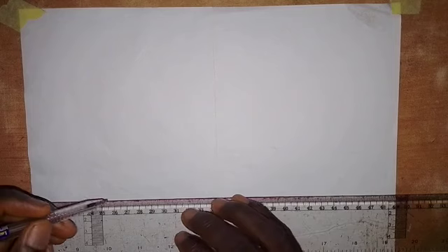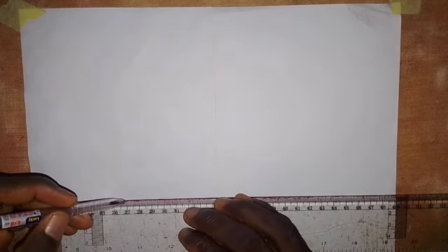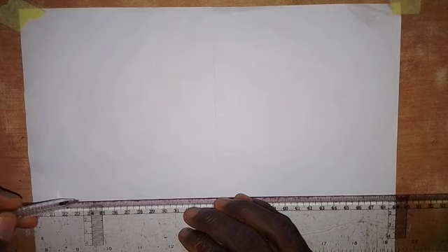Now the first one that I'm going to do is that we have it on a top face of an object. So we draw a line, and then as I've said before, whenever you are to construct isometric circle, you have to draw an isometric square whose length will be equal to the diameter of that circle. For example, if the diameter of the circle is 50 millimeters, you have to construct an isometric square of length 50 millimeters. I hope that is clear.